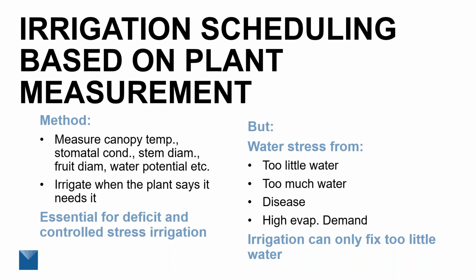That all seems pretty straightforward, but the shortcomings of this method come down to the uncertainties. We can't know exactly how much water is applied without measuring it. We also deal with uncertainties in our estimates of the amount of water lost by evaporation and drainage. We'd be pretty happy if we could measure any of those things within 10%. But if you apply 10% too much water or 10% too little, that effect accumulates over the season.